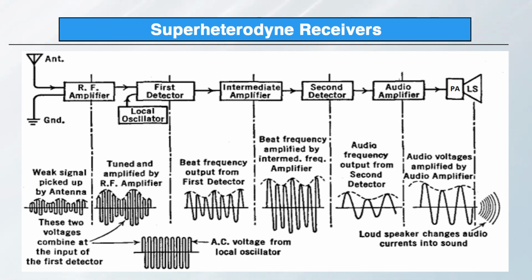Design considerations: it must have high gain, low noise figure and good linearity to preserve signal integrity, often using tuned circuits to select the desired IF frequency and reject out-of-band signals. The next component is the detector. The detector stage in a superheterodyne receiver extracts the audio or data signal from the IF carrier.